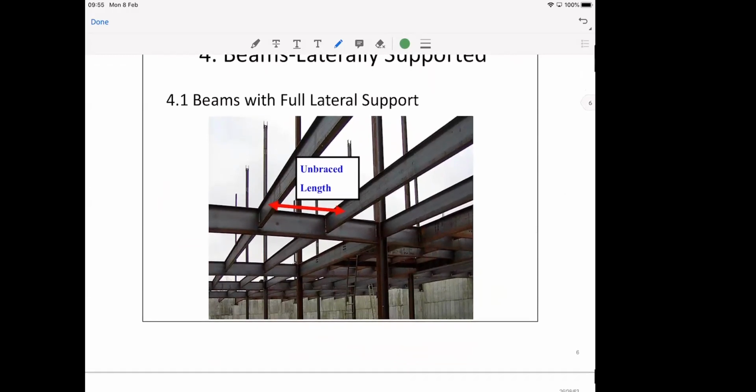So when your beam is not fully braced, say for example, you can see that you now may have this beam. Generally, this blue beam will be the one that takes the floor. So the floor, which is placed in this direction, will help brace the blue ones. The floor will help brace the blue one, so it doesn't help brace the red one. The red one is your primary. This is your secondary, or sometimes they call it a filler beam.